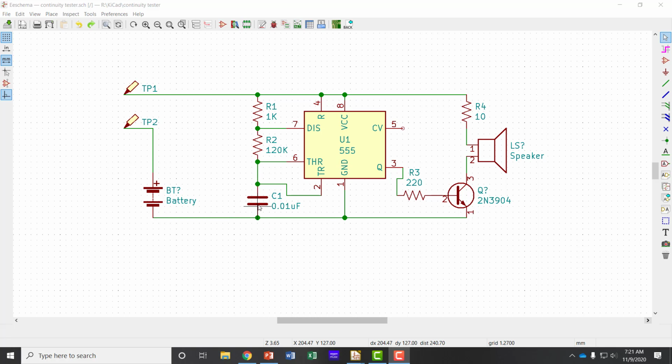We've already mentioned that if you click and drag over a component, it will highlight it and then you can move it. Another quick way is the hotkey M. If you hover over a component, you can press M on the keyboard and it will highlight it. Let's say I want to move this bottom line. I want to straighten this line coming from pin 2 out.